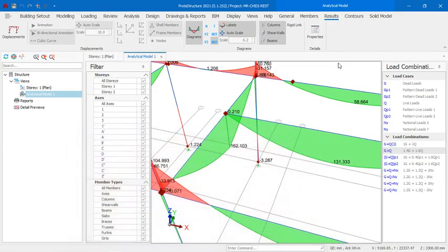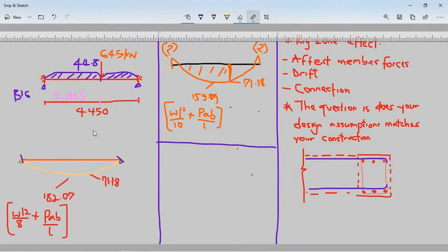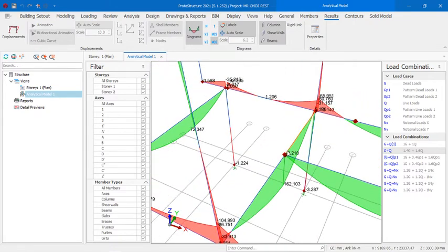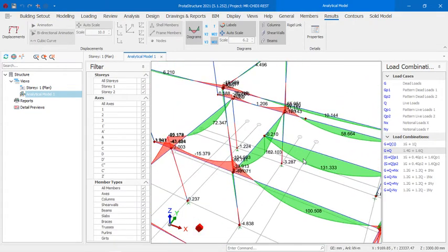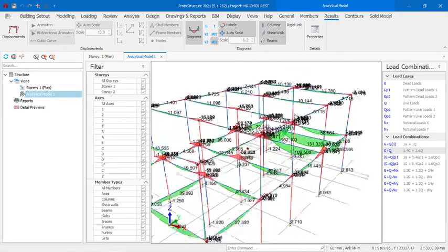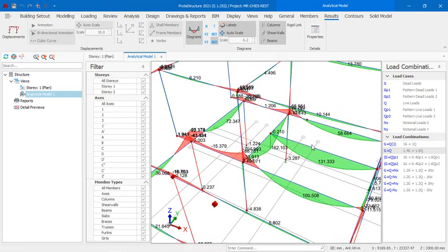But of course, if I have the rigid zone reduced by 25% or maximum, and I see the moment as 128 or 139, then when I do it manually and I see that this is short, then for me as a person, I will be worried. Then I will be questioning what the software is actually doing. So in totality, the software does not have a problem, but it is the user that needs to know what the software does.